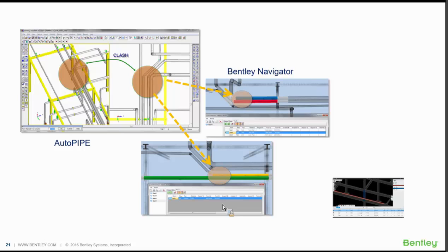The clash list and details that were added by the user can be synced to the project so that out in the field, an engineer can use Navigator Mobile and can investigate them. If the field engineer finds some discrepancies, he could update the clash with new comments, maybe a new attachment or picture, and sync it again for the office engineer to review. And using these tools and including as many components as are actually out in the field as possible will help all disciplines, including those out in the field, work together and avoid costly design mistakes throughout the project.